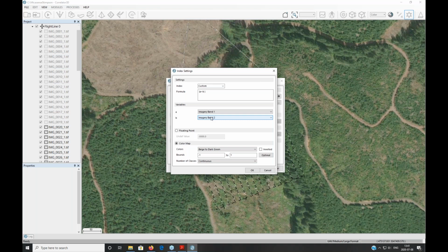If you want to output your typical NDVI, you can go here, select the NDVI, change the order of the bands, take the right band here, so the red will be band number 3, and use the floating option. So we're going to export a 32-bit float that's going to contain your NDVI values as a raster. And all those outputs will be exported as GeoTIFF files.